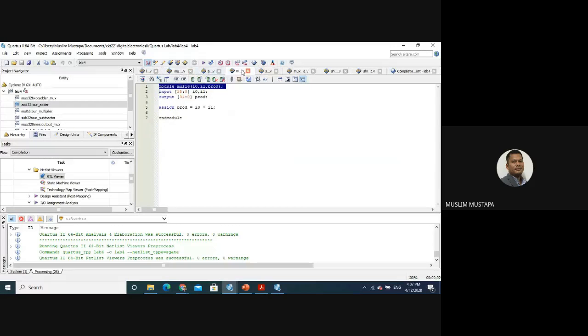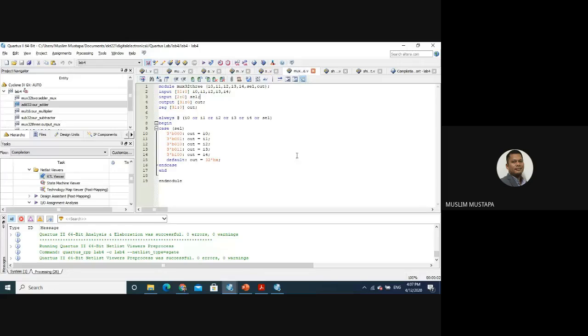There's a select input here, which is where we connect the F. What is the select being used for? It is to select which operation we want to execute. Based on the select input here, either 0, 0, 0 or 0, 0, 1, we are selecting which operation we want to output the result for.